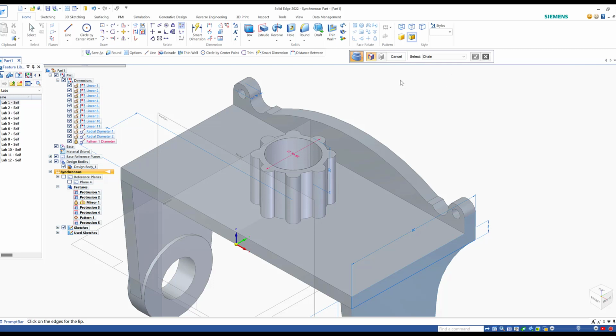In this lip, I need to select where I want the lip. So I'm just gonna highlight this curve, so I'm gonna press shift. I need the lip to connect to this curve, to this line, to this curve here, good, to this curve here, to this line, to the edge here, to the edge here, and to the edge here. So I'm gonna have a lip all over this thing. I'm gonna say okay.